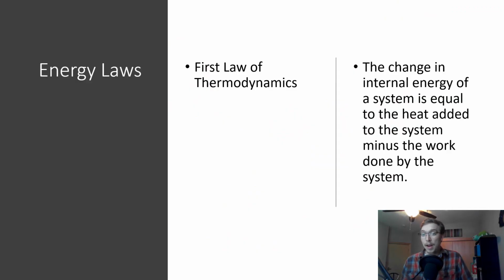Now we're going to get into some energy laws that we do care about. Nothing against Bernoulli, but the first one is the first law of thermodynamics. It is just the application of the conservation of energy principle to heat and thermodynamic processes. It says that the change in internal energy of a system is equal to the heat added to the system minus the work done by the system. What it really comes down to is that energy in is going to equal energy out in some way, shape, or form, whether that's waste energy or pure energy being converted from one form to another.